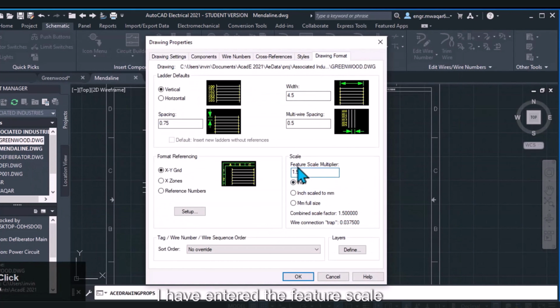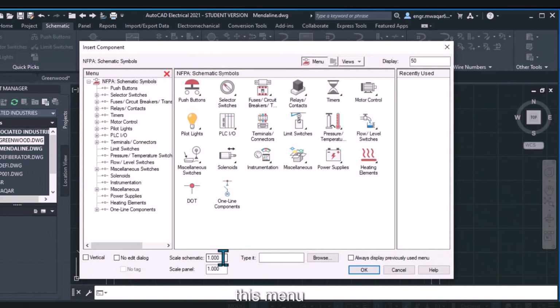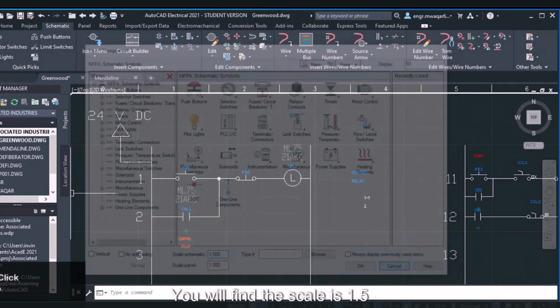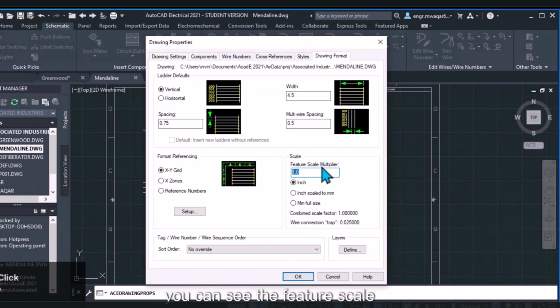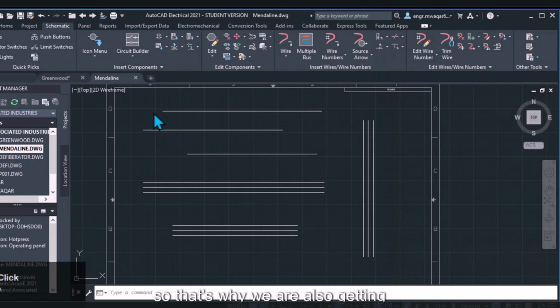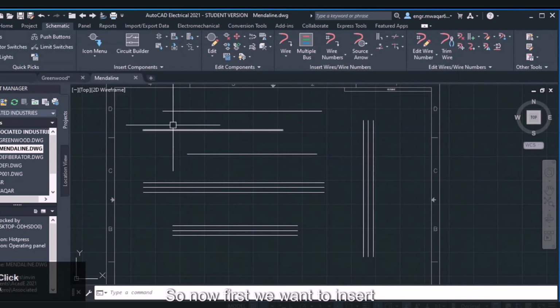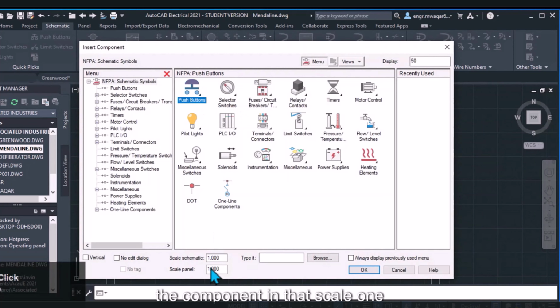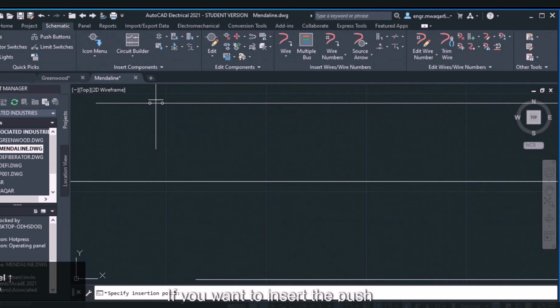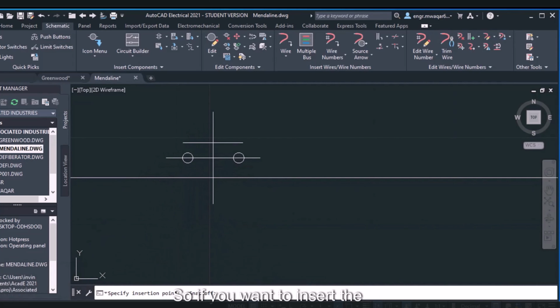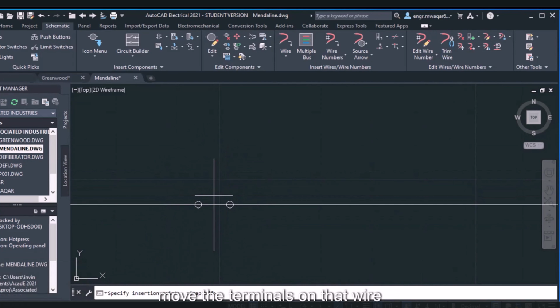And the mechanism behind that intelligence is a specific tagging formula built into the software's architecture. The %F and %N thing, right? Exactly. It relies on those two core variables. The %F is the family code string. So if the database recognizes the geometry of a push button, it assigns the %F as PB. PB for push button makes sense. Right. If you insert a control relay, it tags it CR. A motor gets MTR. And then the %N represents the sequential numbering. It's the unique identifier. Yep.